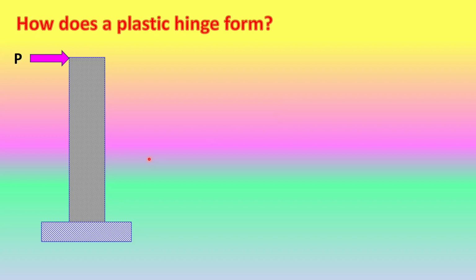For that purpose, we have considered a column having a certain height and a lateral load acting at the top from the left. As a result, on the left hand side, strain and tension will be developed, and gradually, if the force or displacement increases, it may produce cracks like this. With the increase of force or deflection, the cracks will increase in number, intensity and length, and some part of the concrete may also spill out from the body of the column.